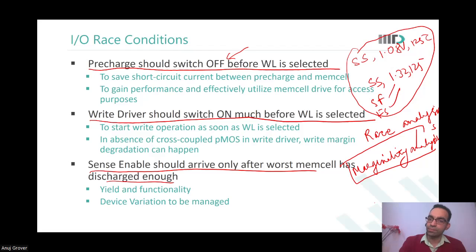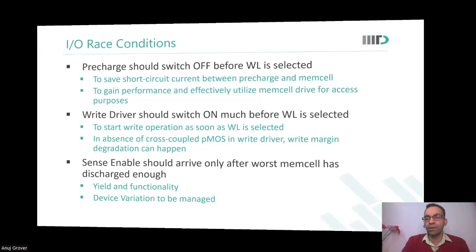So you are saying the margin is the timing difference, the timing margins. And sir, what is race analysis then? Same. Just that after the race, you measure the margin. That is what's called margin analysis, marginality analysis. But someone may also call it race analysis. Which signal came faster? But which signal came faster is insufficient information. I actually need to see what the margins there are. That is why I prefer to call it marginality analysis.